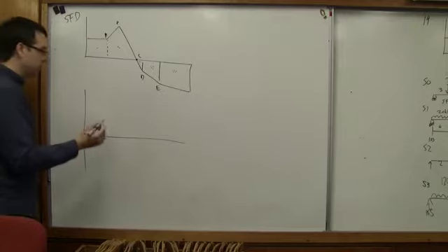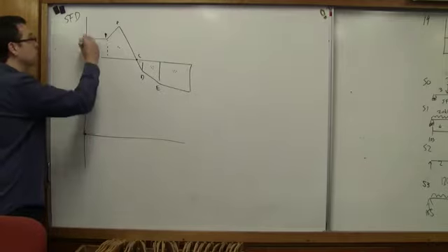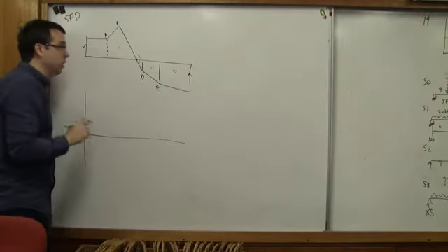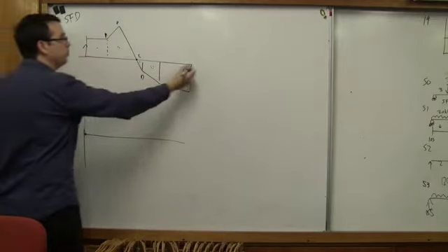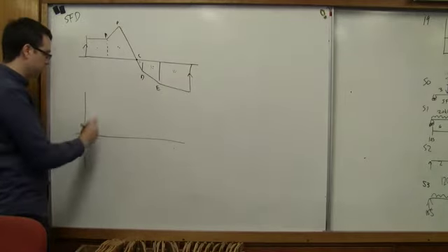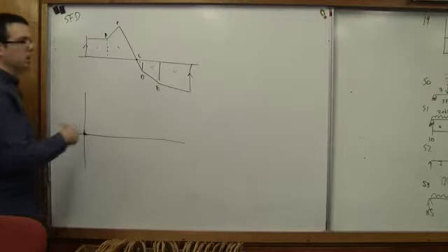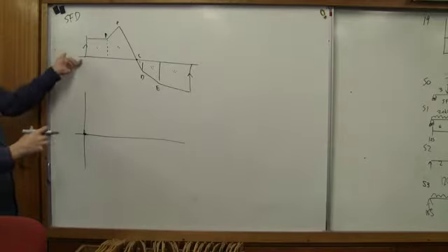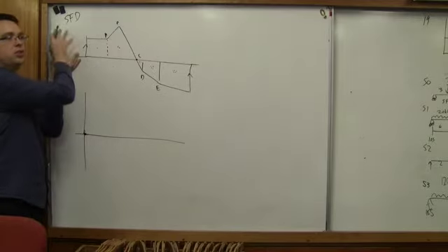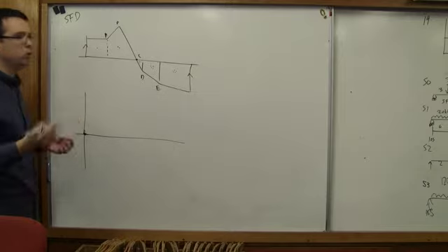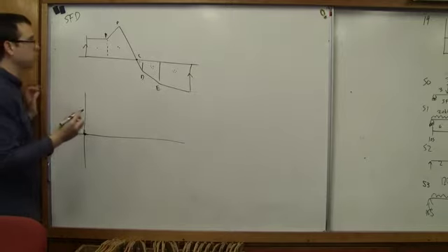Okay, so we always start off at 0. We start and end in 0, and it's often not clear with shear force diagrams and bending moment diagrams that we in fact start and end at 0. And the same is true for our bending moment diagram. So we start off at 0. I've talked about how there is no left-hand side. So if there's no left-hand side, it has to be 0. But if that doesn't make sense to you, don't worry too much. Just know that we start and end on 0 at the end of the beam.